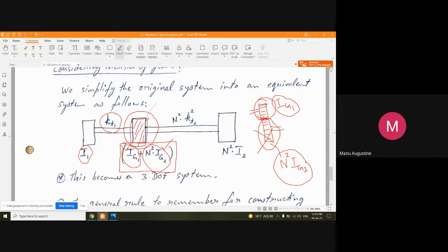And now the only elements that remain or that need conversion are those on the driven side. And you already know what has to be done to the elements that are found on the driven side. You have to multiply each parameter. For example, you want to find out the stiffness of the shaft. Okay, you have to make a correction here. This is not square here. The square will not come. It is simply KT2.